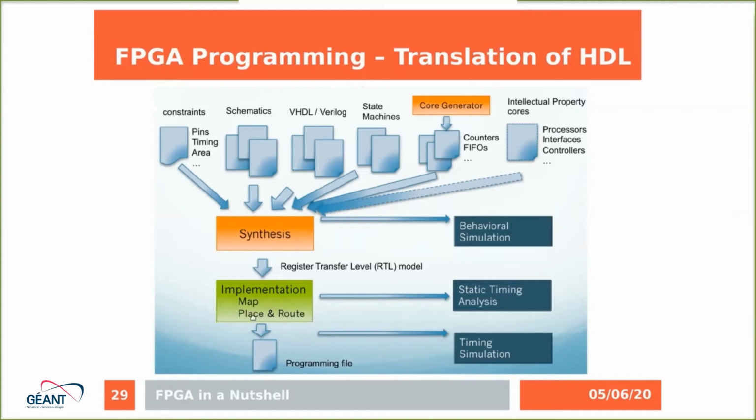This is done in the static timing analysis tool. I will also show you how the static timing analysis looks. After the place and route phase, we can run the timing simulation, which is very time expensive.